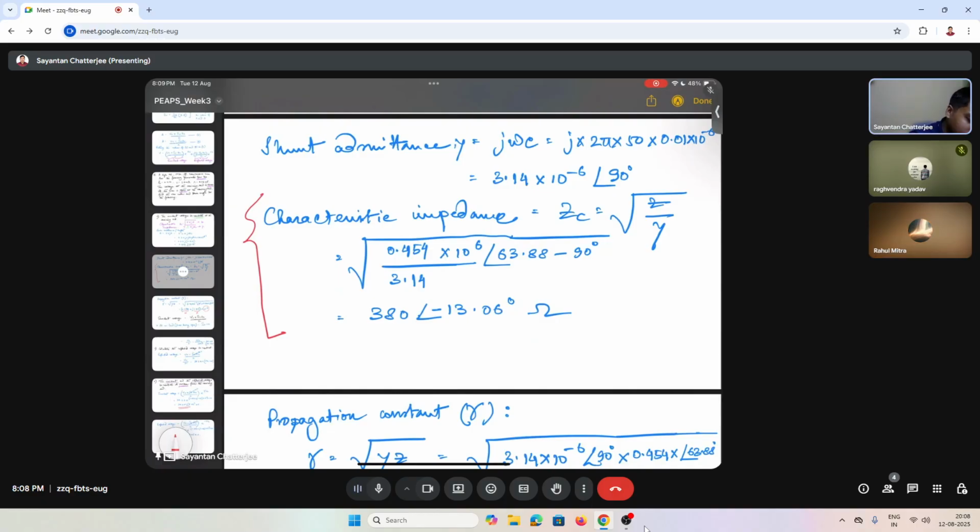Yes, because the power angle doesn't hold linear behavior. In the form of the equation, the power angle doesn't hold linear characteristics. So we cannot assume it will be half. You need to calculate.